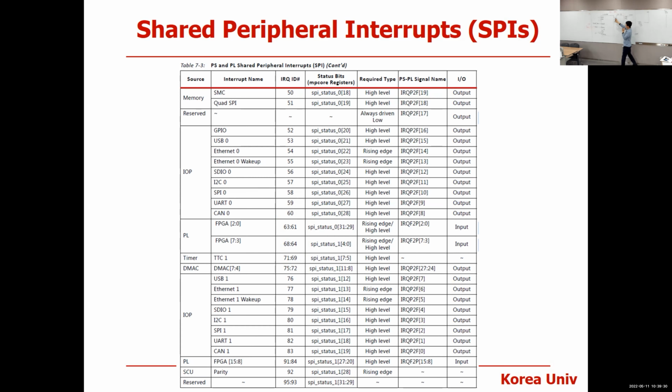The same thing goes for the distributor and CPU interface. The distributor was architected to support up to 1,020 interrupt sources, I/O devices. Then when you license the IP, you can say, I don't need 1,020 I/O devices, I need only 96 I/O devices. That's the Zynq device.